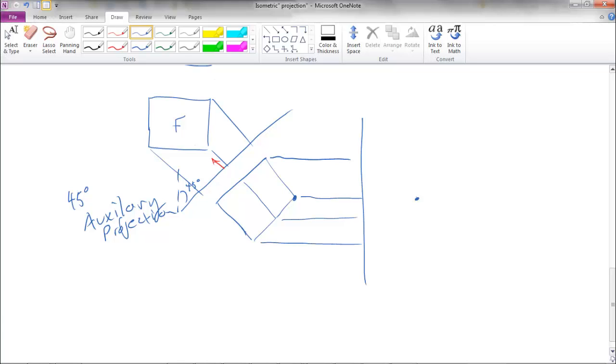And then if we take this bottom one here, we can draw that straight down from it along this bottom projection line and place that here. We can then take this corner here and follow our projection line, place that about there. We know it's a cube, so we can space our points equally.